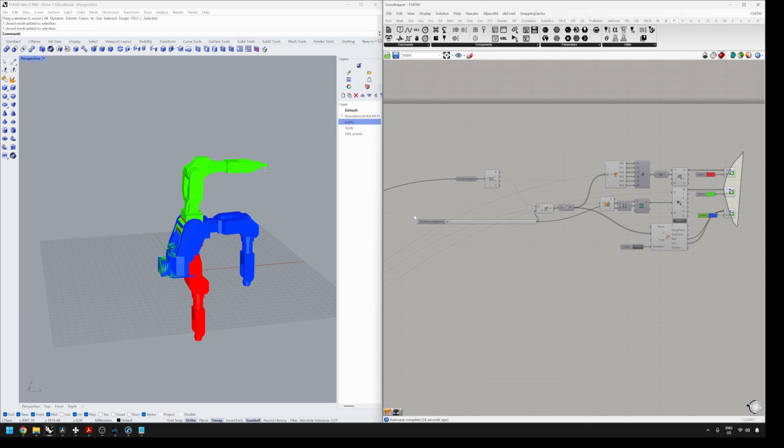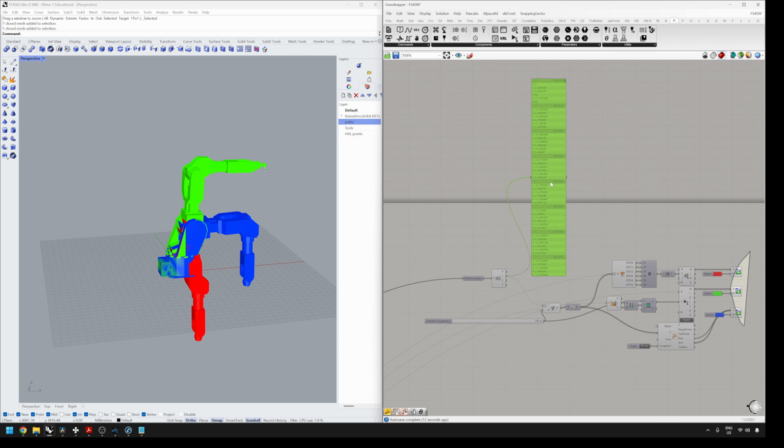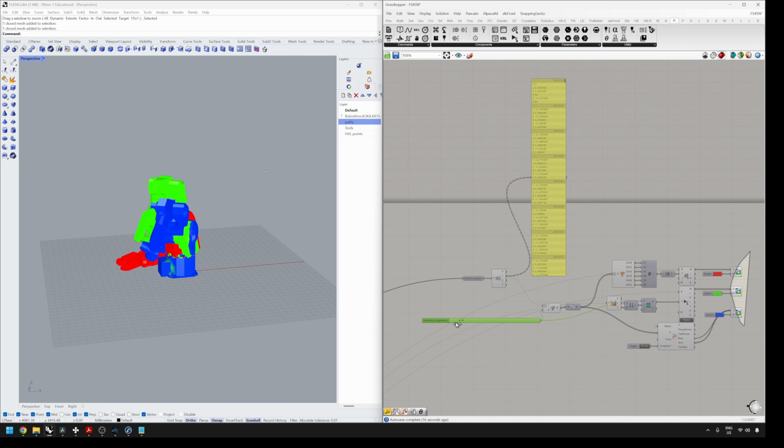I therefore compared 3 available kinematic results using exactly the same joint values. The robot's program simulation in green, the robot's forward kinematics component in red, and the HAL Robotics forward kinematics component in blue. This is where the problem became more serious. All 3 produced different robot positions.